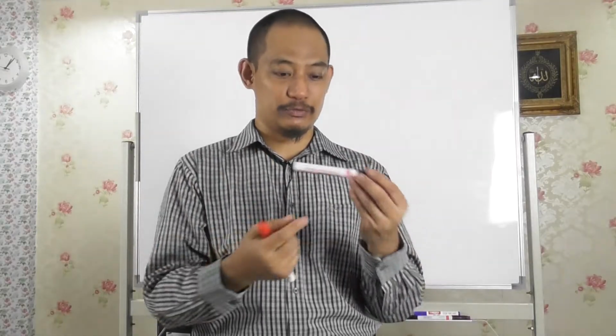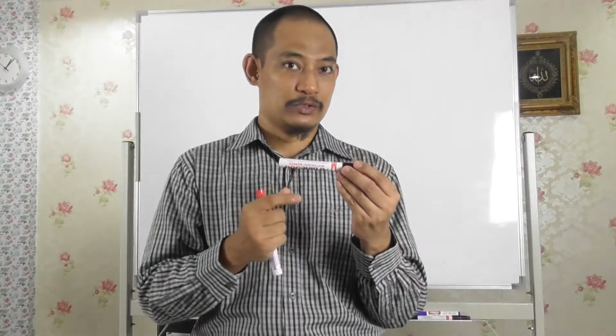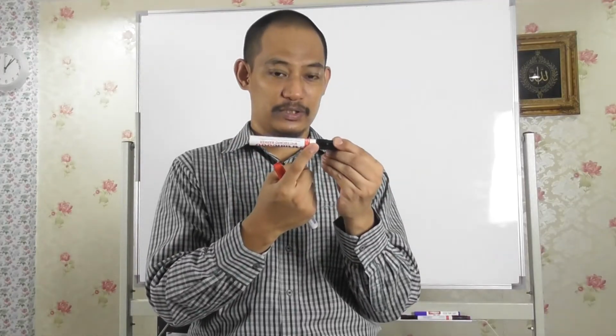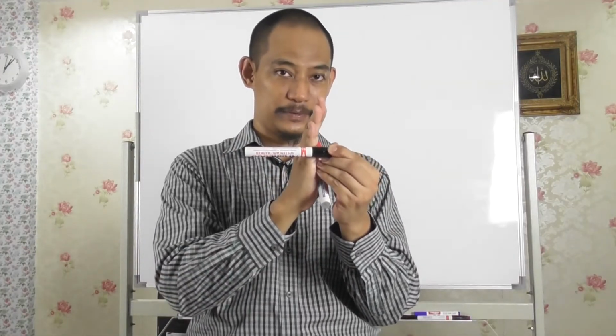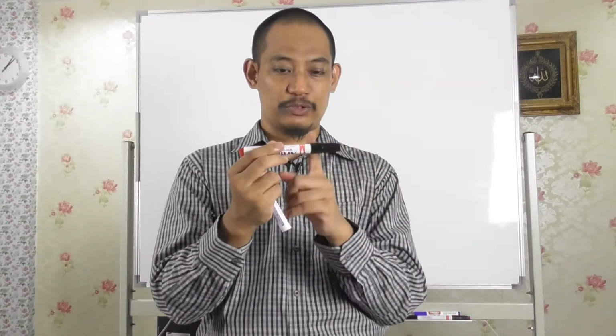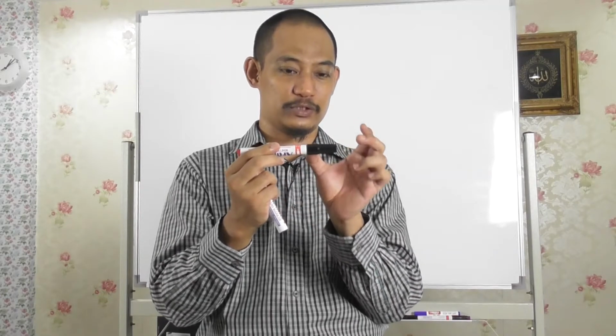The question will ask you to find the internal forces here, or maybe at multiple points. For each point, you have to cut at that particular point, right? For example, if the question says find the internal force at this point, then you have to cut at that point. When you have cut at that point, you should be able to imagine that you have two options, either to focus on this part or the other part, right?